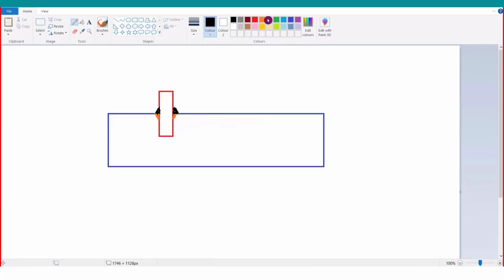Now, whatever process fluid is there, that process fluid is inside, correct? So this process fluid will never come in contact with the outside weld. So the outside weld will not have any corrosion allowance, and its thickness will not be reduced because of corrosion. Correct?